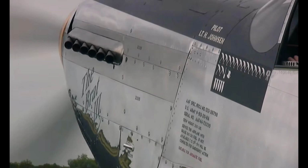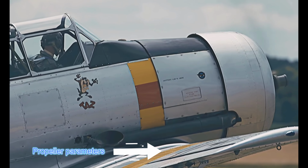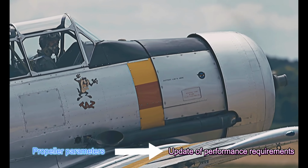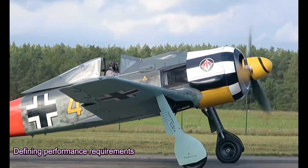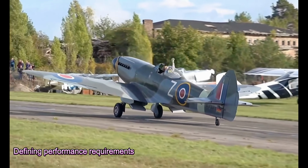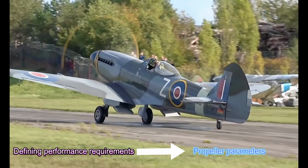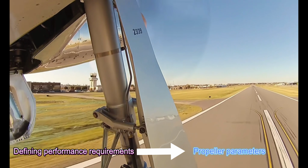As a test calculation, I initially selected the propeller parameters based on experience and adjusted them iteratively to meet normal takeoff requirements. If specific takeoff requirements are defined, such as ground roll distance, V1, or VR timing, the propeller parameters can be derived in reverse from these targets.